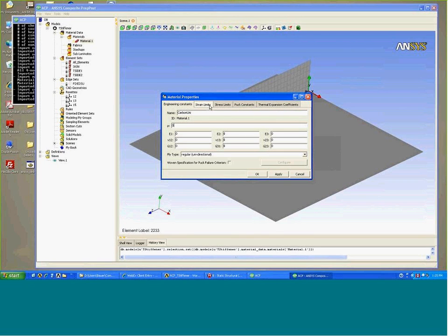These three tabs allow you to define material allowables, such as strain limits for post-processing, comparing results, and defining failure conditions and failure post-processing. For this carbon unidirectional material, let's first enter an example density.